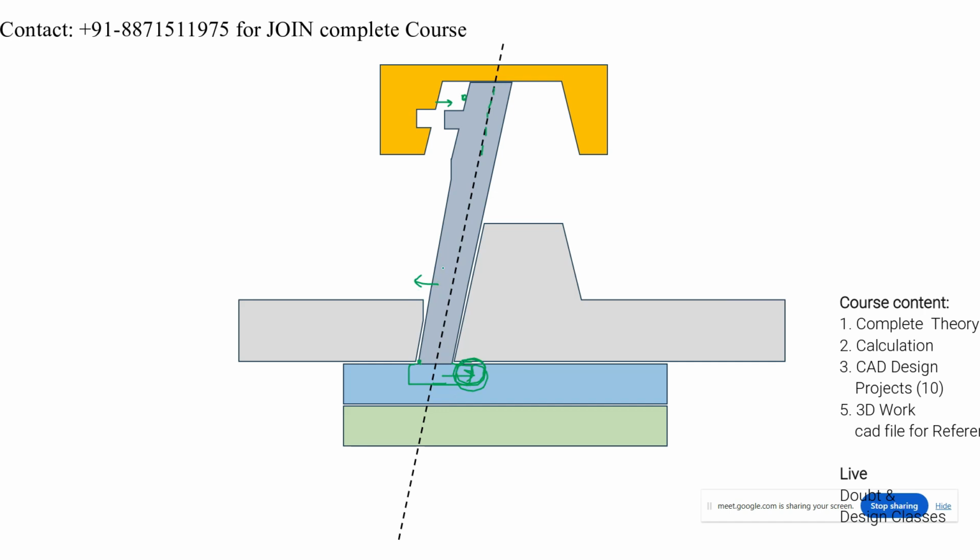This is a rod, the complete component, a rigid component. It is not flexible like a sheet or a strip. This is a rigid component of MS or C45 which we are using. So if this is moving here, it will move here also, and that's why we have to take the clearance here also. So we have to provide the guide rail.